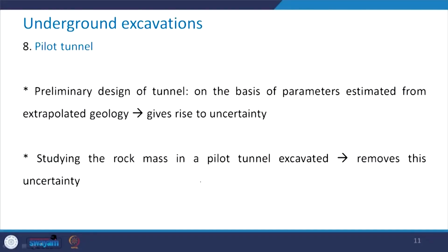So, as far as the pilot tunnel is concerned, the preliminary design of the main tunnel on the basis of the parameters which are estimated from the extrapolated geology gives rise to uncertainty, and therefore studying the rock mass in a pilot tunnel which has been excavated removes all this uncertainty.